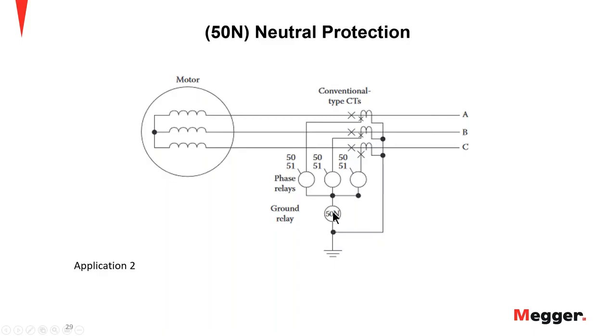This is just like we have here. The physical size won't be an issue because we're connecting in the circuit, and we don't actually have a CT that we're going to be running through with each individual motor or the return. And then we also need to make sure that we set this above any false residual currents that can result from unequal performance or high unequal offset starting currents. This prevents the probability of false relay operation as well, as long as the CT burdens are limited to the voltage developed by the saturation of the CT.